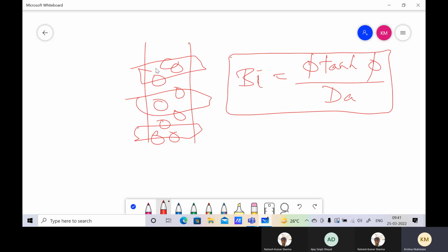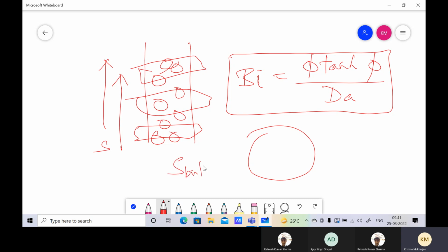Notice that both internal mass transfer as well as external mass transfer will tend to become more dominant as the column moves up, because substrate concentrations tend to decline. As the substrate goes up, the bulk will be low. So if this is low, then this is also low, and then inside is also low. So both are declining. Do the relative contributions of internal and external mass transfer change as the column goes up? Does the Biot number change? This is an interesting question that I leave you to answer. It is not an easy question.